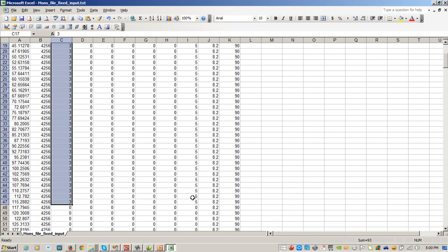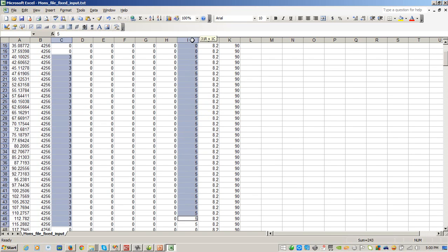Let me just highlight it here so you've got a really good picture. Here you've got your G signal and your steer signal. Now here, steer is going to be to the right, and I'm going to select my AY as being positive. I'll show you how to deal with that in ChassisSim in just a tick. Once you've got that, you save it as an ASCII text tab delimited file.